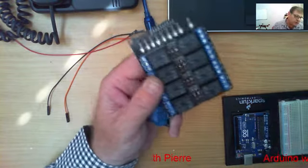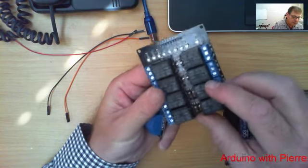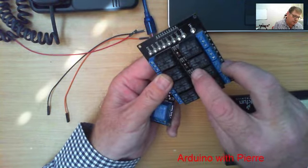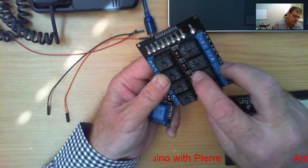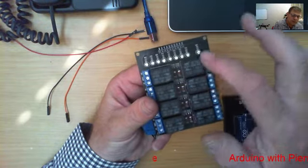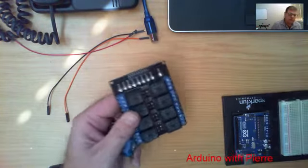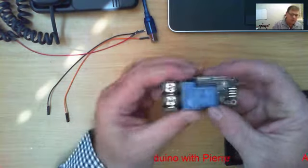Now these relays are rated for a specific current, and in this case this one is rated 10 amps 240 volt AC or 10 amps 30 volt DC. That's the maximum current and voltage that this relay's contacts will be able to handle. Now if you want to switch higher current devices, you need a different relay.